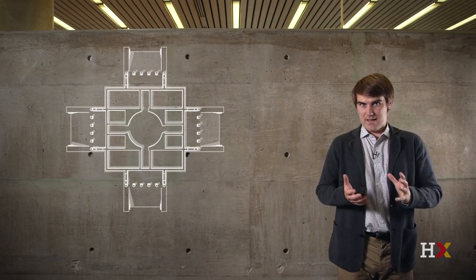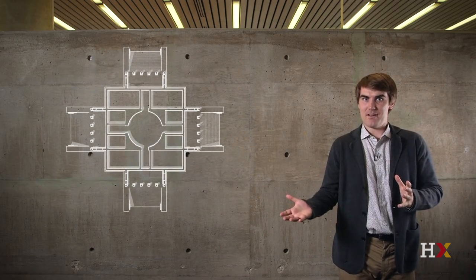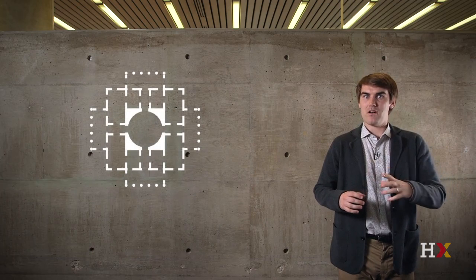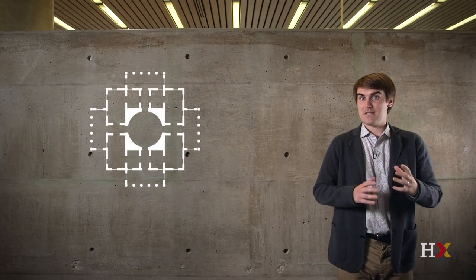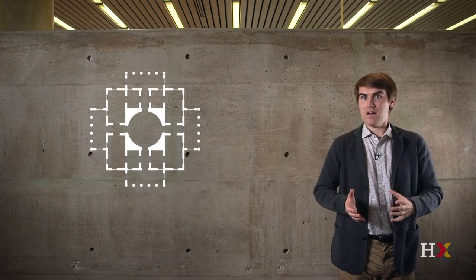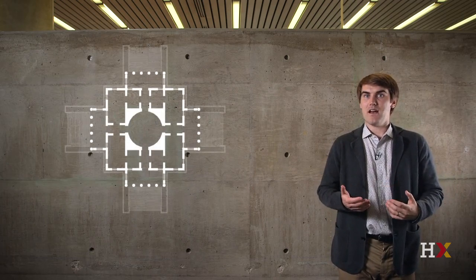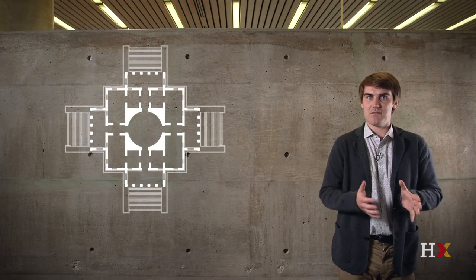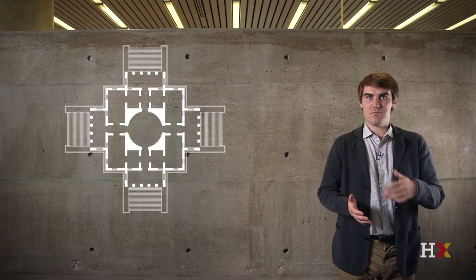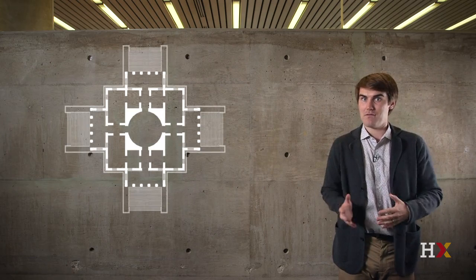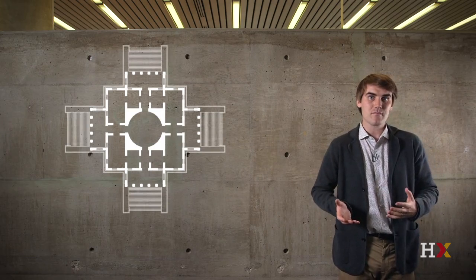And as we look at the plan that we now see has been cut, we notice how the area that's enclosed by the walls or by the columns has been darkened. There's a single line when we have a window, and there's a solid infill when we have a solid wall. So as we look at the plan, we can see how the different spaces connect to each other, through which doorways we could move, how we enter the building by going up the steps, by turning left or turning right to go into a different space.